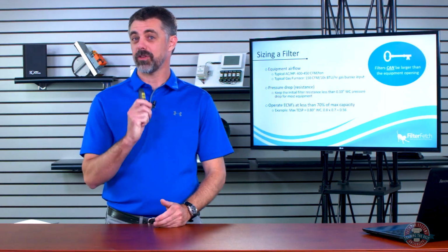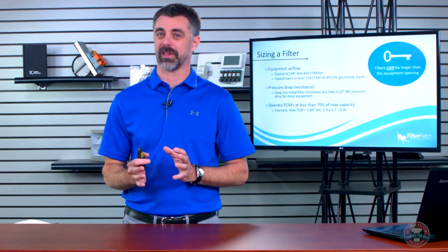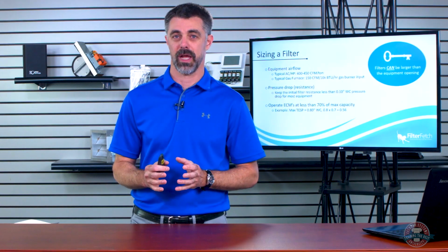Ooh, that's a tricky question, William. I like it. The rated static pressure drop on filters can be difficult to find. A lot of manufacturers don't publish it, but I'm going to give you something tonight on the next slide, so keep your eyes open. But really, you need to go back to the filter manufacturer because each filter is slightly different, okay?